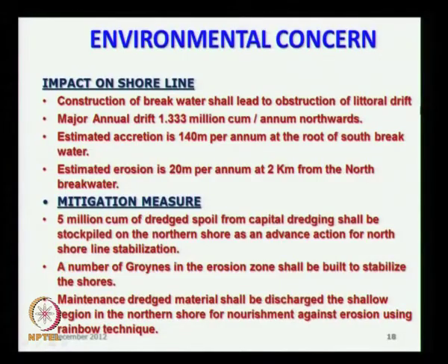What are the environmental concerns? This is what I started in the beginning. When you want to build a breakwater, there will be certain issues in the environment. What are these issues? One is the construction of the breakwater will lead to obstruction of littoral drift. The major annual drift will be about 1.333 million cubic meter per annum northwards. There will be a southern drift also, but northern drift is about 1.333 million cubic meter per annum.